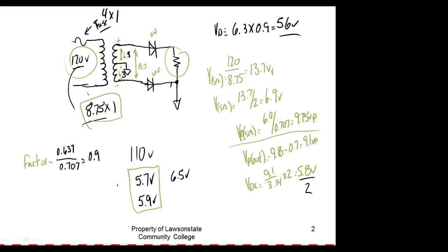So let me erase that. And the next one, it would cause a pretty good error. So if you want to use that, that's fine. It's not on the formula sheet. I'll try, if I got room, to put it on there. That formula sheet is pretty packed. We can go directly to it, but this is an approximation. And what's nice about an approximation is if I go there and I measure 0 volts, we got a problem. If I go there and measure 3 volts, I got a problem, right? You understand? I know something's going on. Either the transformer lost some coils, which happens a lot.